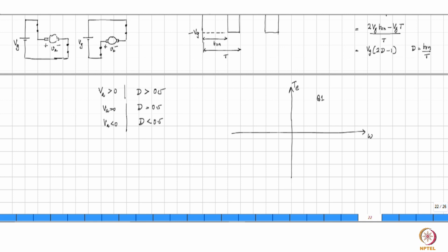Now obviously you may want the motor to be increasing speed all along, and as you reach the place where it's going to be put down, the speed has to be decreased and it has to come to 0 right at the point where the object has to be released. You cannot have a non-zero value of speed when the object is going to be located there, because if you go with a non-zero value of speed and keep it there, you are creating a mechanical impact and it's likely that the object will break.